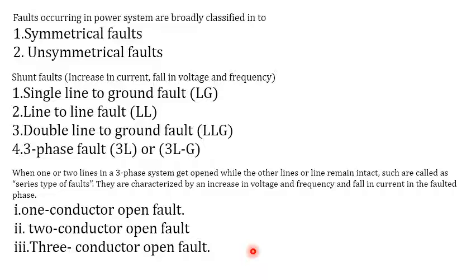It involves phases of different magnitude and phase angle for each phase. Analysis of this unbalanced condition can be carried out on a three-phase basis, but this is a very cumbersome process. There is a simpler approach: the method of symmetrical components and sequence networks for determining the voltage and current in all parts of the system after the occurrence of the fault.